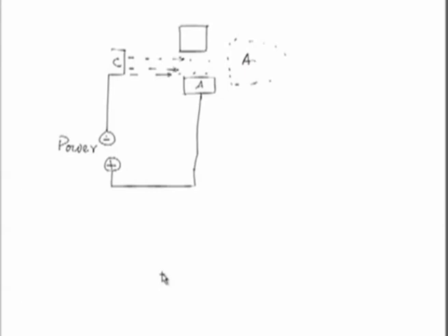So, this is the Ar gas, and this argon gas will be ionized by these high moving electrons, and these argon ions will be focused or accelerated towards a particular point or a focal point, which is nothing but the surface of the workpiece material.